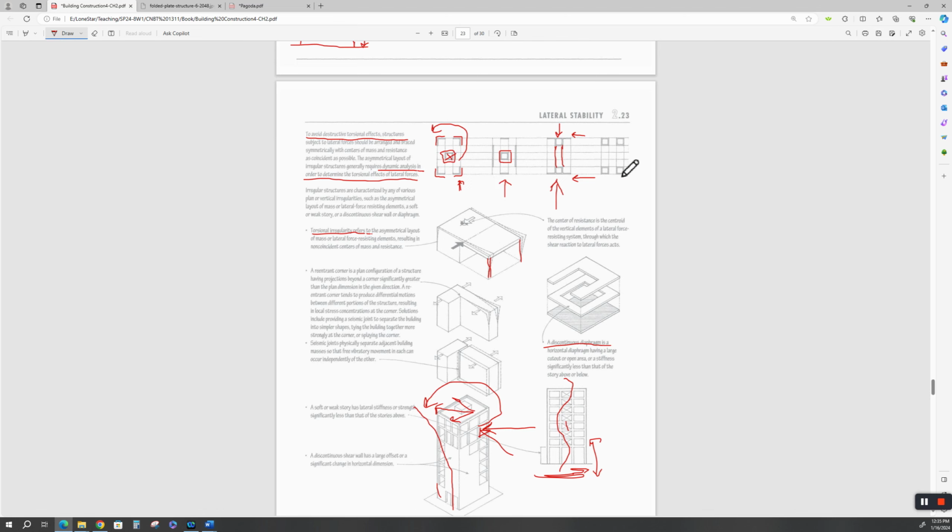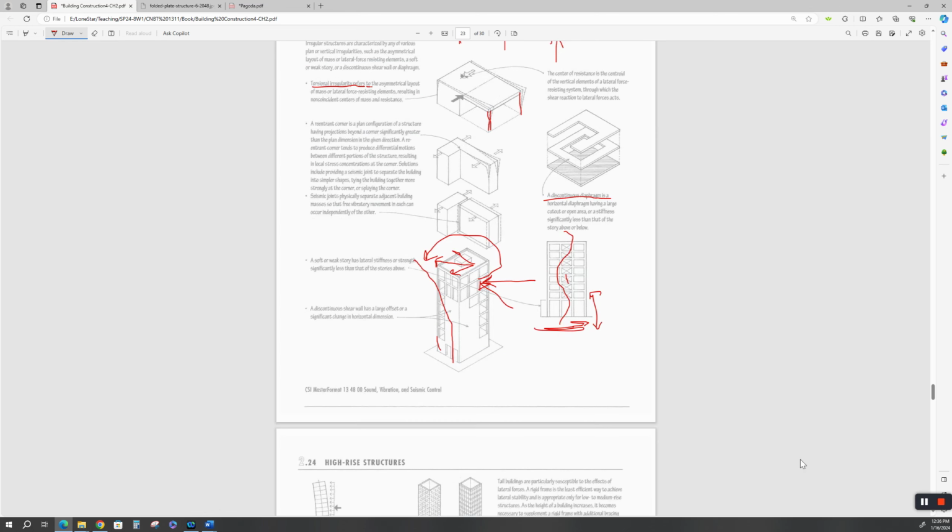Okay, all right. Here we have another concept. Maybe you'd use one of these for all your plumbing and these two for elevators, who knows? Or maybe this is a high occupancy building and you've got 4 elevators in here, and you'd use the elevator core as your 4 big shear columns. And of course you've got to tie the rest of the frame to them so that it all acts as one. Again, your mileage is going to vary, and your creativity. As long as you understand the balance of forces, you'd be surprised what you can do.